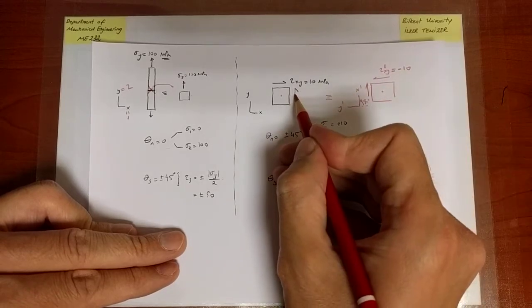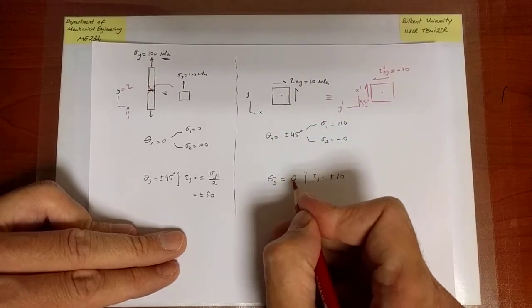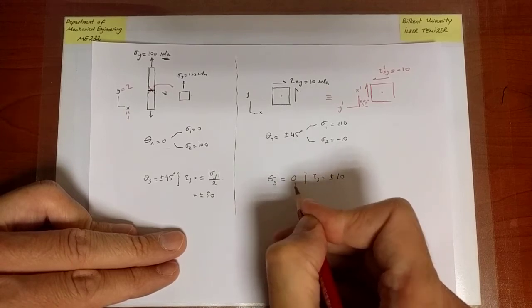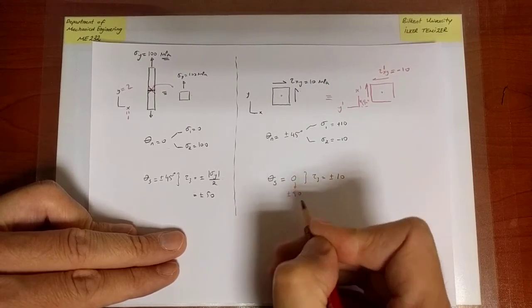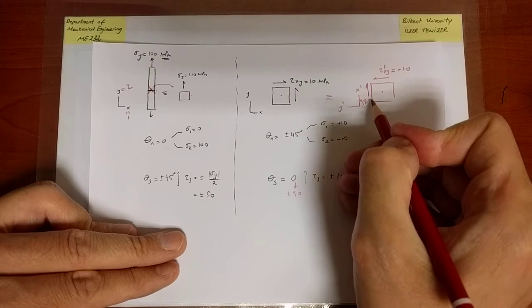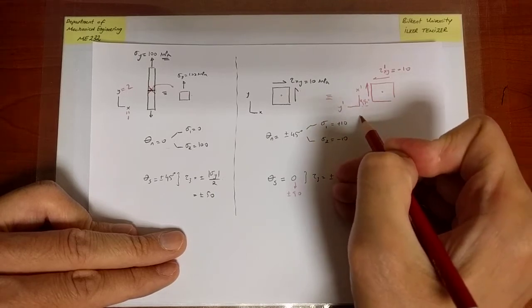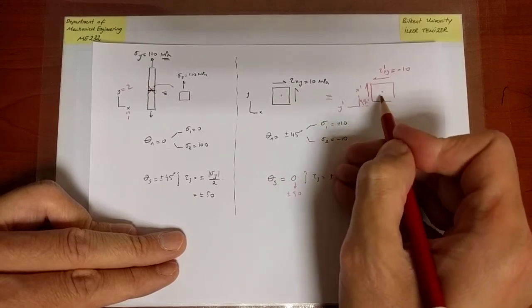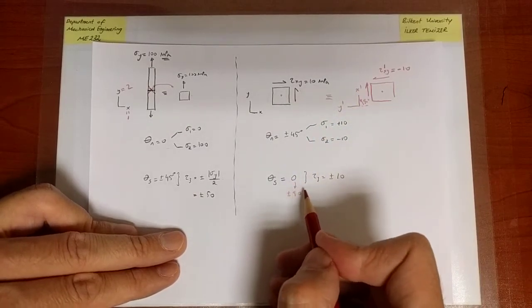So there is a principal direction, theta s equals 0, but remember, there is another principal direction always that is at an angle of plus minus 90 degrees with respect to that direction, right? So that is, for instance, plus 90 degrees, or I could have rotated by minus 90 degrees, still I would get the same picture. That is the other corresponding principal picture.